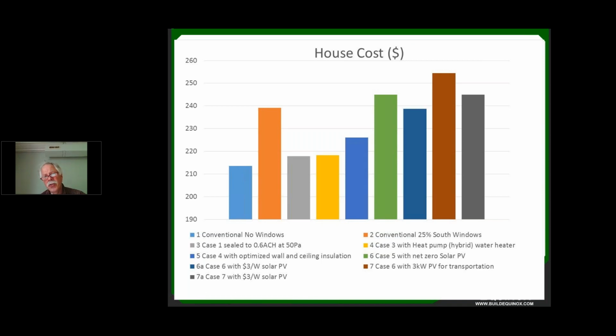Commercial building, an institutional building on our campus at the University of Illinois, where I've been on the building committee. The windows cost $100 per square foot versus a well-insulated brick wall, which the A&E firm estimated at $50 per square foot. I mean, if that doesn't tell you only put in windows where you need them for view and where you need them for daylighting, I don't know what would. And in the case of a university, these are scholarships that aren't going to be made if we put expensive costs into fancy frills on the building.